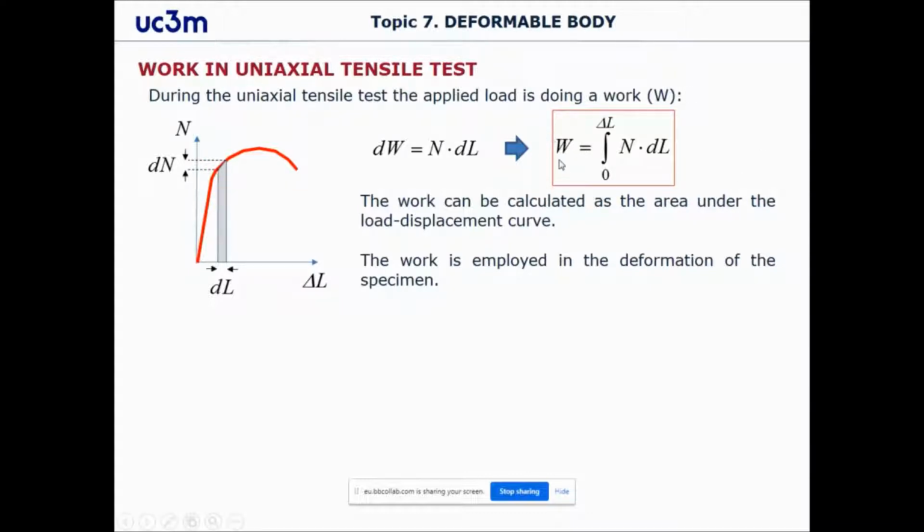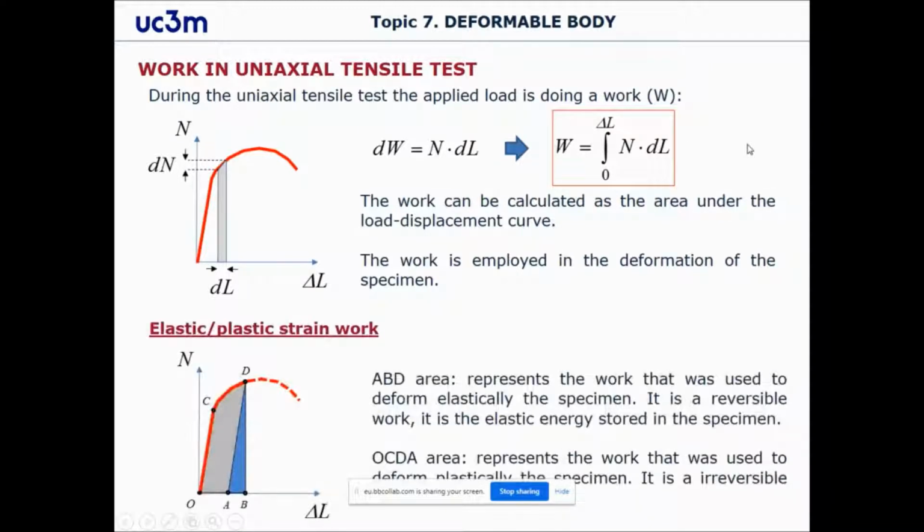So this work that is carried out is given by the load that we're applying, right? And the deformation that we are achieving, right? And if we want to estimate the amount of energy that has taken to deform a material, we need to do the integral between 0, the initial position, and a certain deformation of this quantity, right? So in that sense, we can estimate the amount of work we have applied, and that in certain ways is a certain amount of energy that is stored in the material.